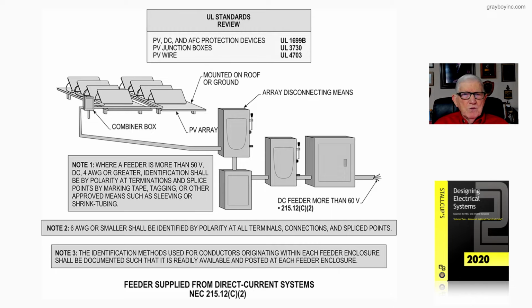And due to these systems such as wind generators, wind electrical systems, PV systems, DC is produced. And so they wanted to mark these where the DC was routed before maybe it was put in a converter and converted to AC. Now UL gives us some UL standards to use, as you see in the boxed in information.